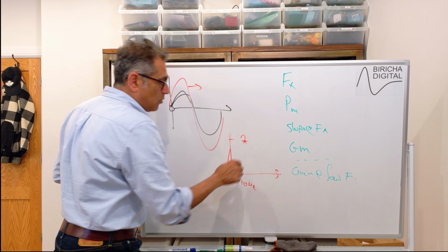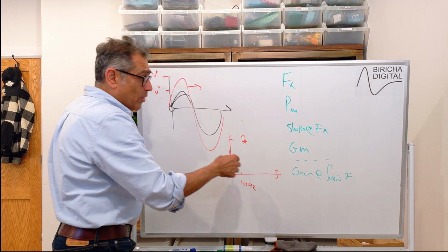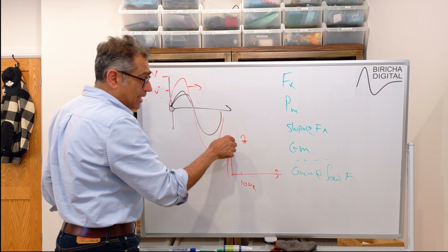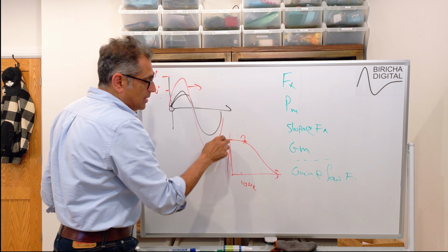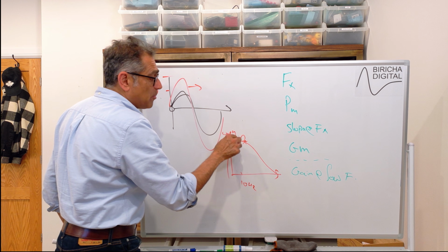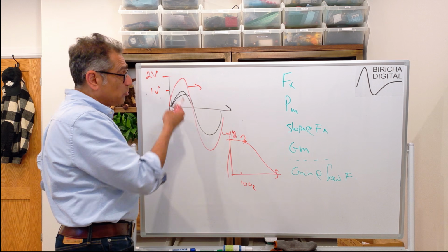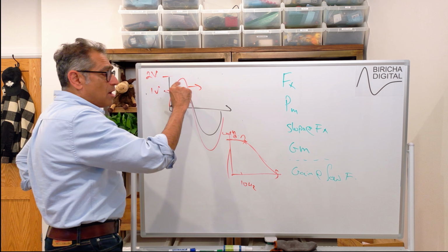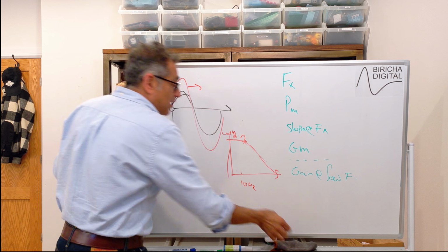2. There we go. And then I do it again at 20 hertz, 30 hertz, 40 hertz, and all the way, and I end up with a gain plot. Now, in our particular case, it was a low pass filter, so that height would be smaller. It would look like this, where this is 0 dB. Remember that we plot things in dB. Again, we have done another video on how you convert from normal linear gain to dB, and it shows how this height will change. The other thing that can happen is that there will be a phase shift.